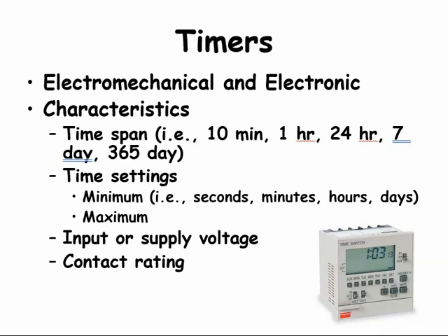Timers are like relays in that they usually have load limits, which is described by the contactor rating that indicates the maximum load that the timer can be used to turn on and off. You will have a chance to use a timer in one of the labs.